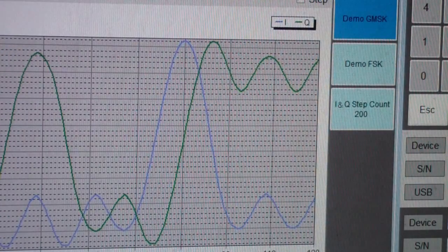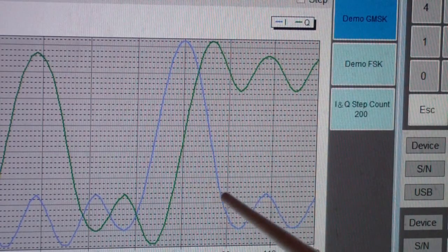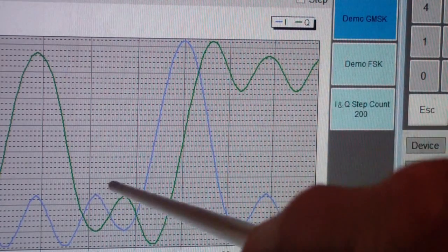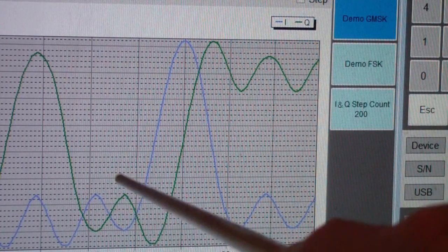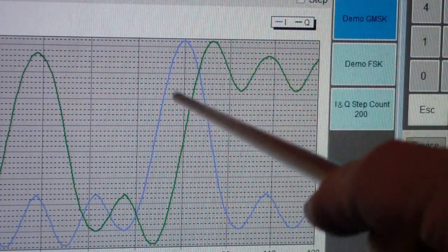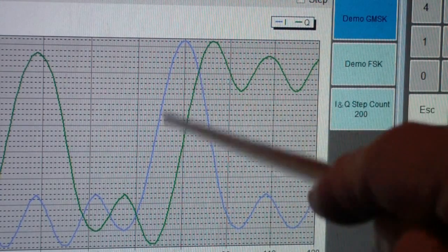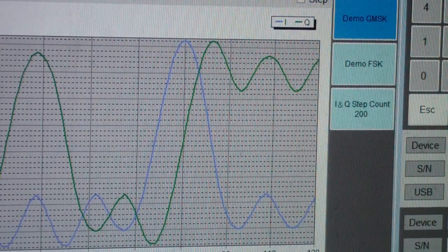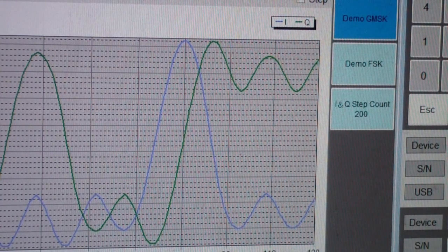That is accomplished by adjusting the baseband using a Gaussian filter. And this is the actual raw data that is applied to the I and Q modulators to produce that Gaussian effect. Now, when you're working in the digital domain, there really isn't any distinction between digital filtering and any other kind of digital signal processing.